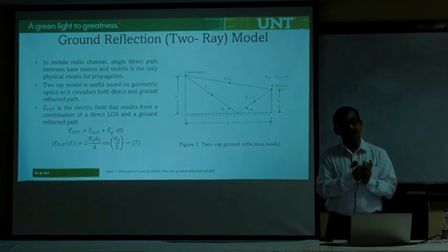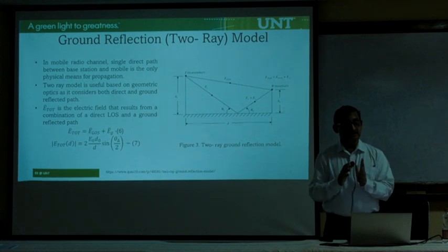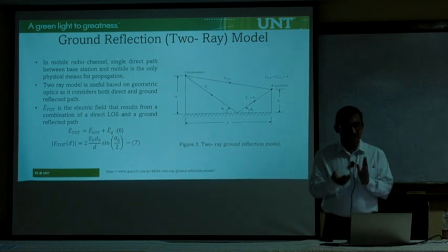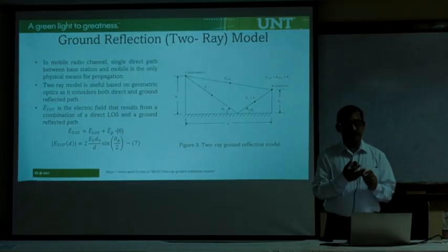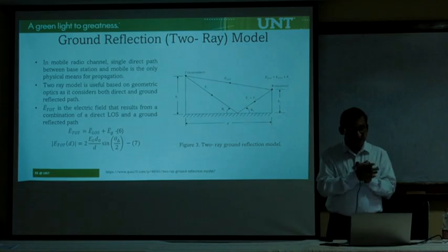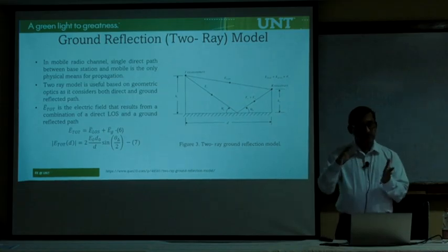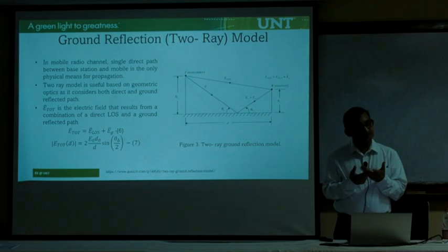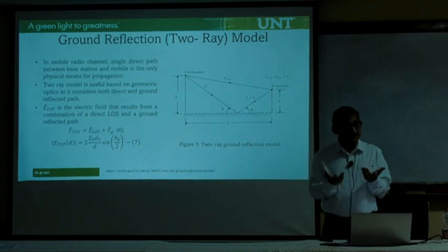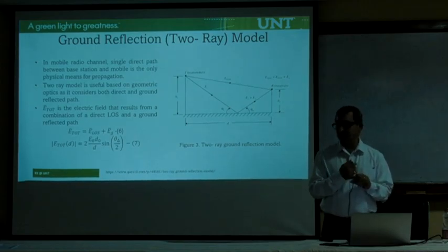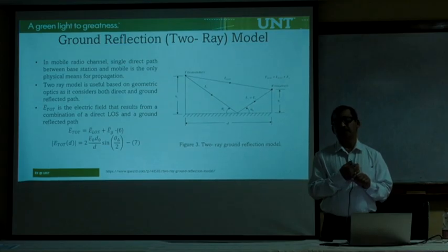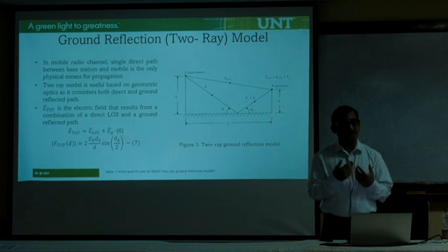But what you need to do is develop techniques at the receiver to deal with them. For example, you can design a receiver to effectively collect all these multipath signals, and then see whether you can add them constructively. There is something called a rake receiver that does something like this. The second thing is multi-input, MIMO, for example. It is also a means of effectively dealing with this.